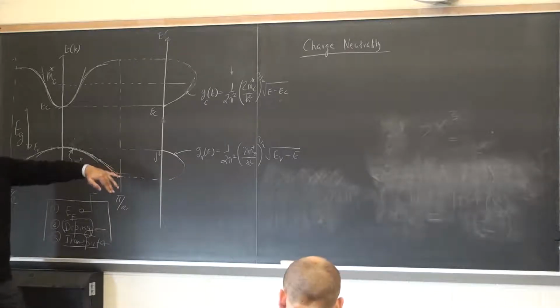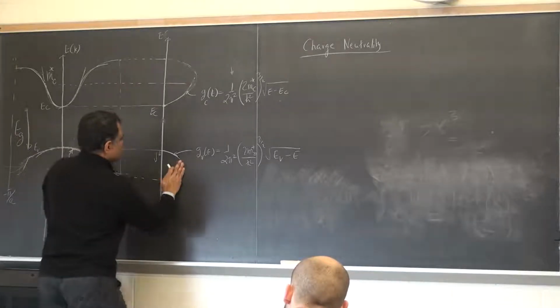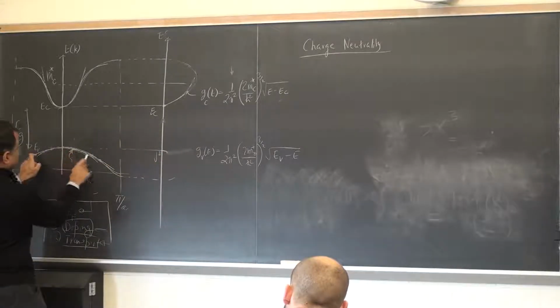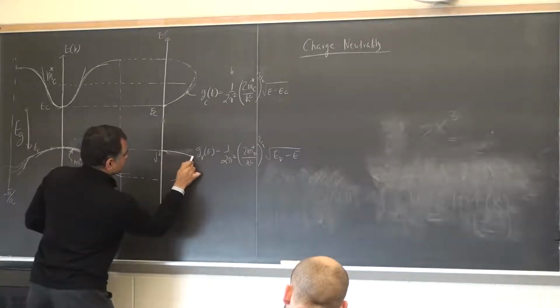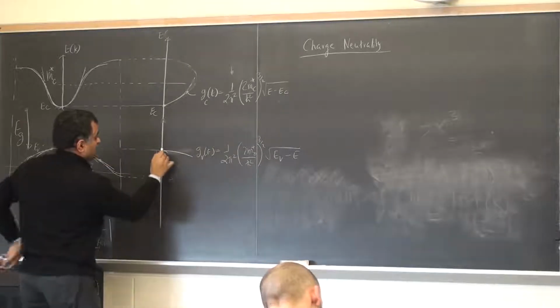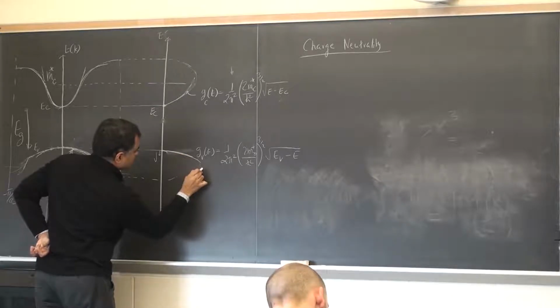So that's the valence band density of states and conduction band density of states. The way I've sketched it is misleading. Because the mass is heavier, the density of states is larger. It's larger because the mass sits in the numerator, to the 3/2 power. Okay? So it will kind of look something like that.